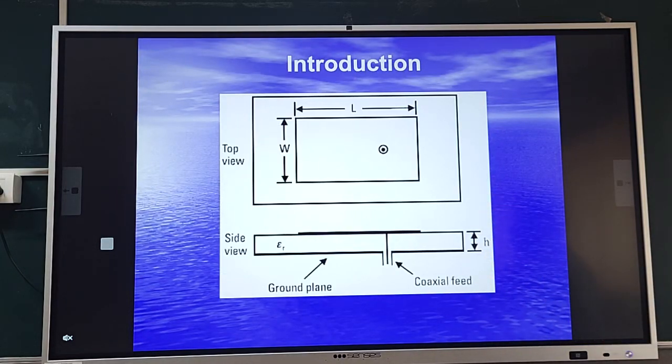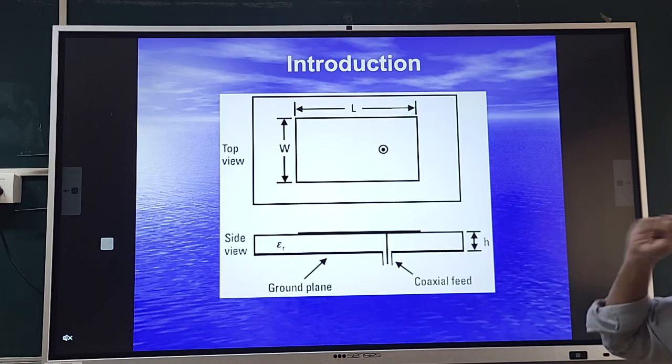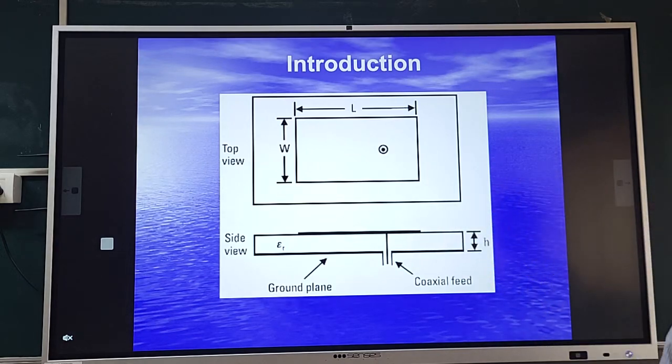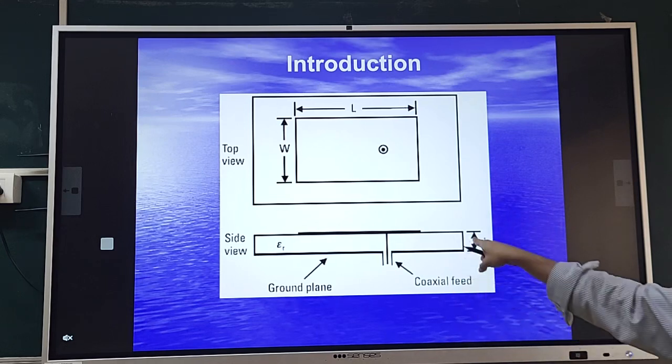So here I am bringing down the charge storing capacity, or the capacitance, of this antenna. In that process I will make the antenna more radiative in nature. Another aspect is the distance D. In microstrip antenna design, generally thicker substrates are used. H should be larger.